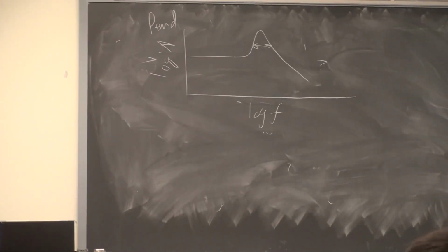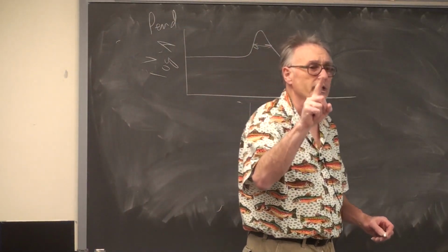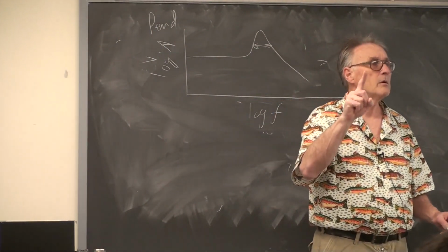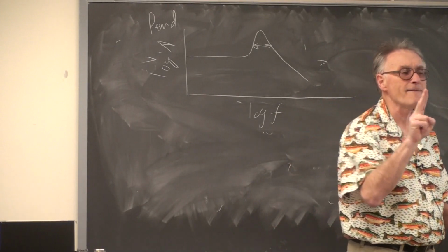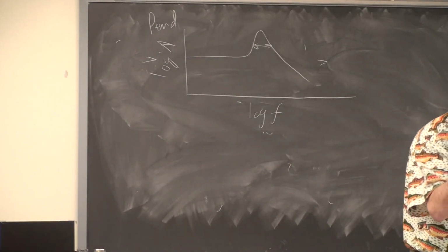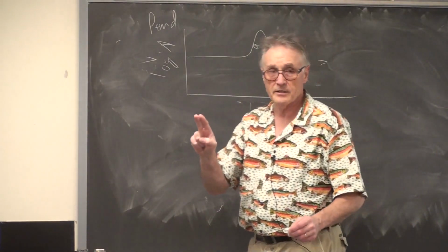You'll probably just use the damping coefficient, which is given by how many cycles, more or less, does the system undergo before it stops. For your pendulum, the friction is going to be dominated by two physical effects. The first physical effect is that the potentiometer has internal friction, and that will slow down the pendulum. The second is, unless you're very, very careful about the way you route the wires coming off the pendulum, those will add to the friction and slow down the pendulum.